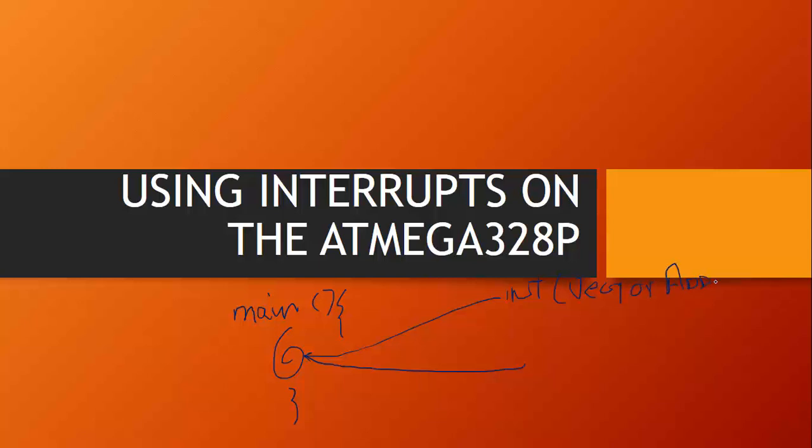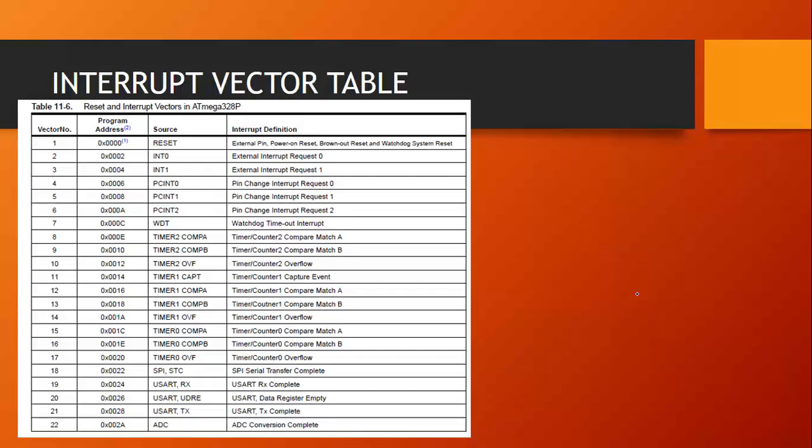That vector address is basically where you are telling the controller to go, where it will find the subroutine that it should execute as part of the functionality you want should that interrupt occur. So the vector address is always associated with interrupts, and we have multiple vector addresses.